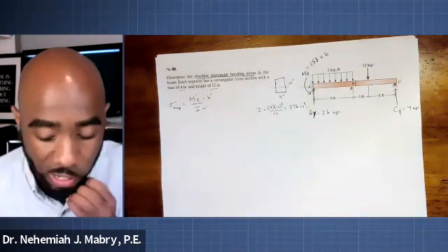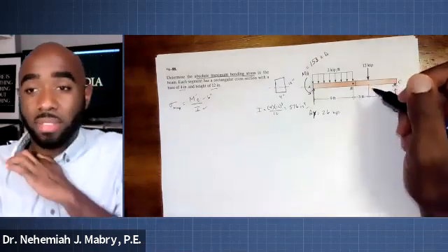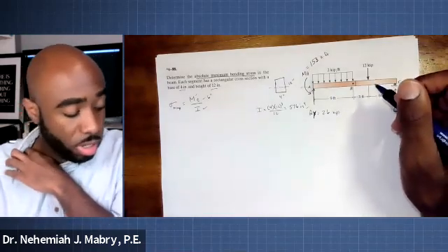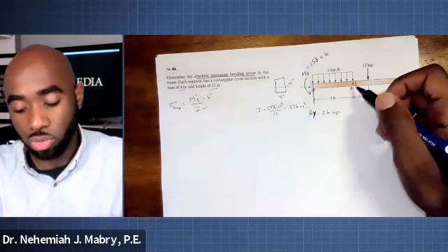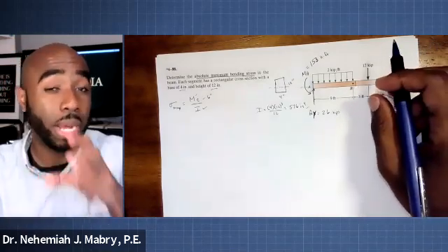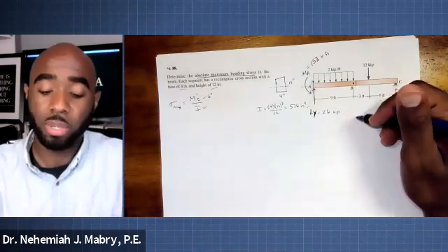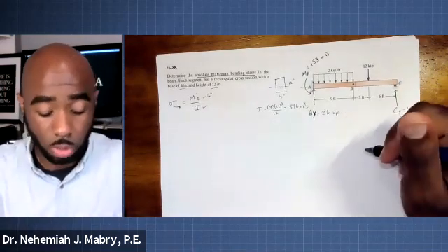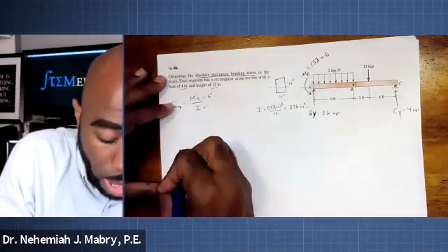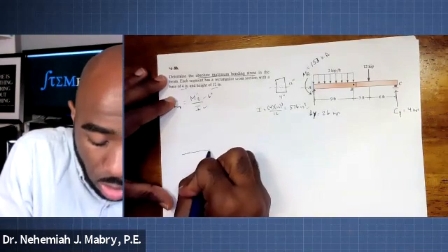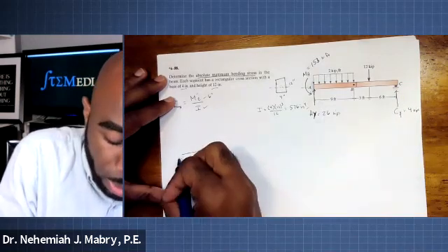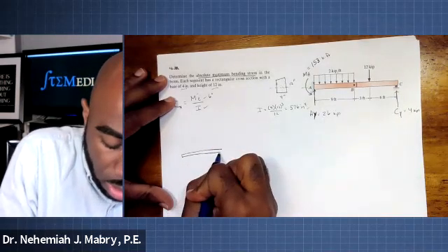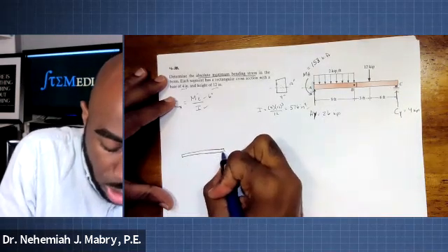Now, here's how you do it when we have this hinge involved. We know that at hinges, the moment is always equal to 0. So let's remember that when we get ready to do our moment diagram, the place that lines up with that hinge should be equal to 0. But here's what you look at: you're basically going to divide your beam up into 2 parts.